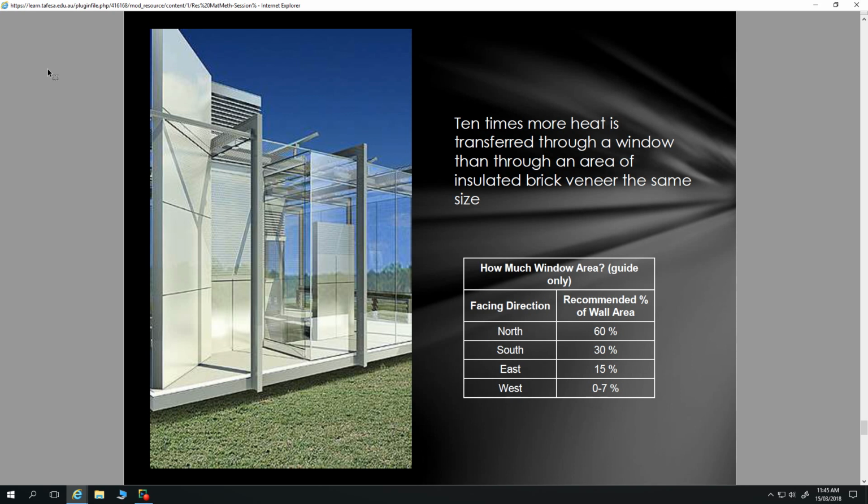we really minimise the heat and light getting into the house, and then we're only getting that full wash of sunlight from around, let's say, 5:30, as opposed to from 3 o'clock in the afternoon. So we're cutting down our period of full sunlight into the building by providing shading to the west in that fashion.